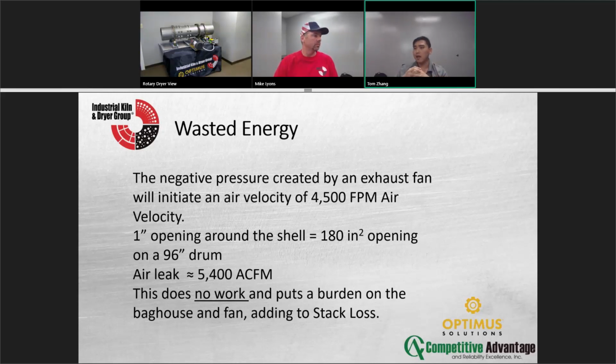I'll tell you a story. We did a frac sand plant that had a combustion chamber, and they were right at the limit. Because they had air leaking into the dryer, they had to increase the ID fan. Well, what happened when they did that was they had an undersized baghouse, then the pressure went up. Then they have alarms on the baghouse, and then guess what? The operator turned down the fan. When they turned down the fan, the combustion chamber got hot, and then the combustion chamber got melted. So that was a very expensive issue related to seals.